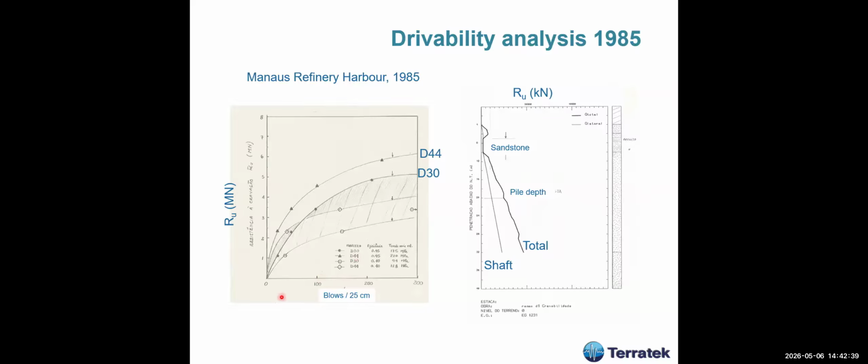And this wave equation, we enter the characteristics of the pile, of the soils, etc. And it gives me these kinds of curves for different types of hammer. And then we can select the hammer for the strength of the resistance of the pile during the time of driving. And this is the strength of the pile during the time of driving that we estimated through static methods, which I'm going to show you later.